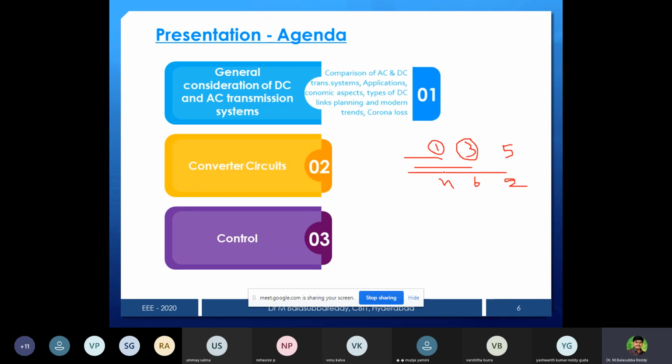So there are different types of devices, meaning series and parallel operation we need to consider. In that case, how many devices are connected in series, how many are in parallel, that is the choice of converter connection. There is a series and parallel combination of a commutation group. That is one group we call, let it be 1 1, then 1 2, and so on, up to 1 R, and similarly 2 1, 2 2, and so on, then S1, S2, and so on, up to SR. So this is the way we connect.